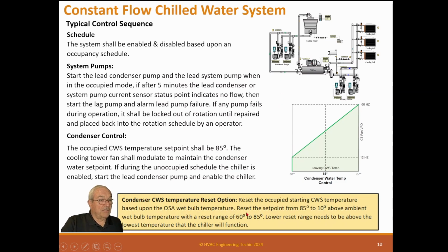There's a plant here, a 20,000-ton plant, that ran one year one way and ran the next year the other way and compared the weather data. And they saved a lot of energy. Now, what happens, of course, is when you lower this temperature, this fan starts to run more. But this fan running more, which is much smaller than the motor in here, makes a difference, but not a very big difference. It's still best to lower the lift of this chiller as much as possible, even though this fan speeds up a lot. It runs at high speed much more than it normally would.